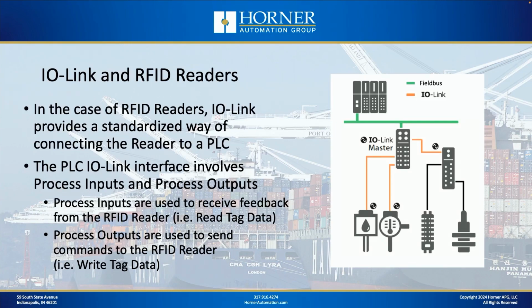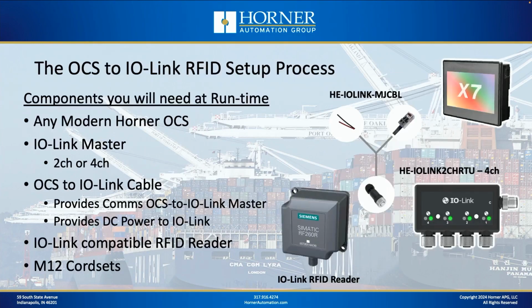So as we read data from the tags and as we read status from the reader, that's all coming in through process inputs. As we're sending commands to the reader to read or to write tags, then that is all handled through process outputs. So really, that's where all the work is done in the application today, beyond just getting the initial configuration done, and that is manipulating those process inputs and process outputs.